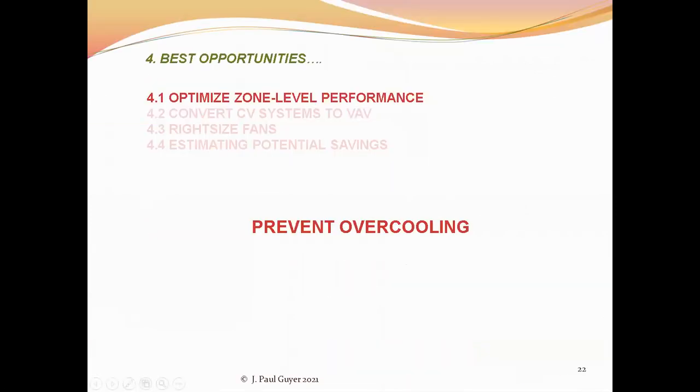Now, overcooling. If you are dealing with a reheat system, performance needs to be evaluated to keep the cooling level as low as possible. For hot water reheat systems, that is where you can have a hot water coil providing the reheating rather than an electric resistance heater.